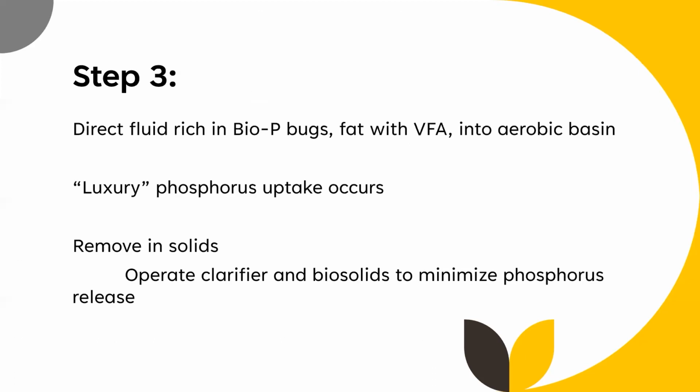The third step here is directing that fluid that is rich in the BioP buds that are fat with VFA into the aerobic basin. You will have luxury phosphorus uptake occur here in the aerobic basin. Once that phosphorus has been consumed into the biology, it needs to be removed, and that is done in the solids, with the clarifiers in most facilities.